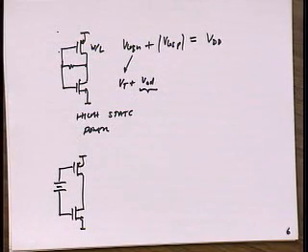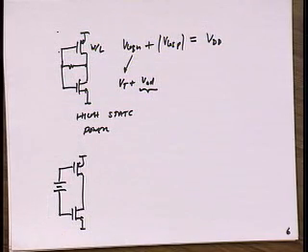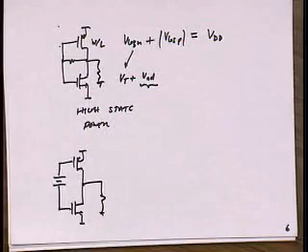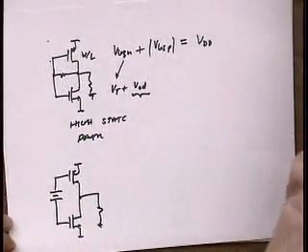So instead of putting a battery, if we put a, say, capacitor and bias the two devices separately, can that be done? Yeah, so this battery could be a capacitor, but then the problem with a capacitor is leakage, right? So in a switch capacitor system, I could do that, right? I could keep charging up that cap to the right voltage. But if it's a continuous time system, I couldn't do it. And usually if you're driving a resistive load, it's a continuous time system, right? Usually.